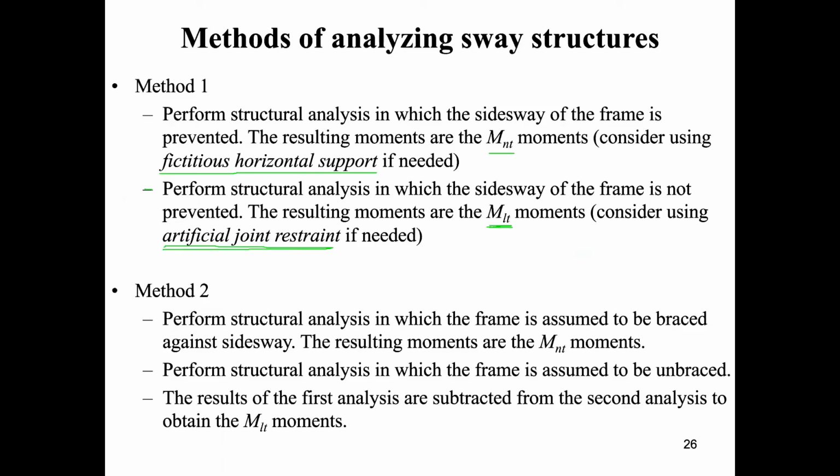Method 2. Perform structural analysis in which the frame is assumed to be braced against side sway. The resulting moments are the no translation moments, M_nt. Perform structural analysis in which the frame is assumed to be unbraced. The results of the first analysis are subtracted from the second analysis to obtain the lateral translation moments, M_lt.